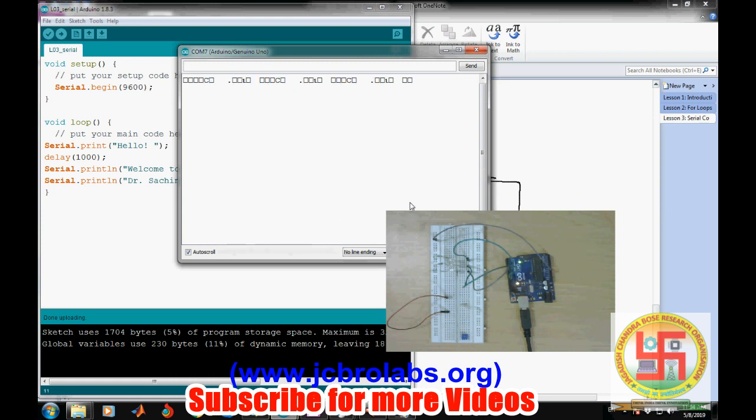Okay, so this is what we were talking about. Suppose device 1 is talking too fast, but device 2 is not receiving that fast. That means you will not get anything. So in order to understand the data meaningfully, device 1 and device 2 have to be operating at the same rate, which is 9600 baud rate in this case.